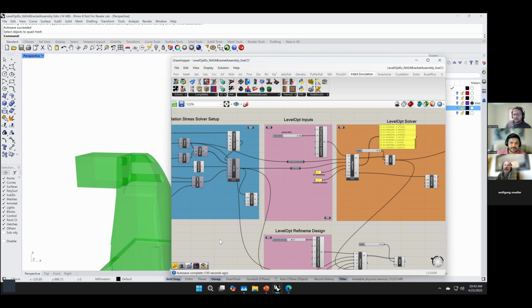Can it support lattices, the optimization? If you just use the black box, it will just try to move the boundaries based on the sensitivities. So if it was a gyroid, you might end up with something else. But if you wanted to optimize preserving the parameters, then you may have to look at just the velocity and then come up with a way to update the lattice parameters if you wanted to preserve the lattice type.